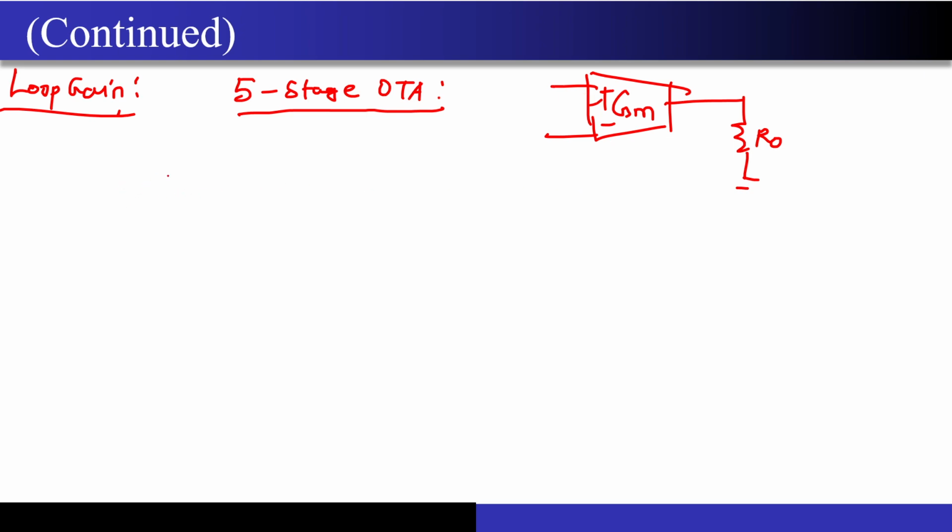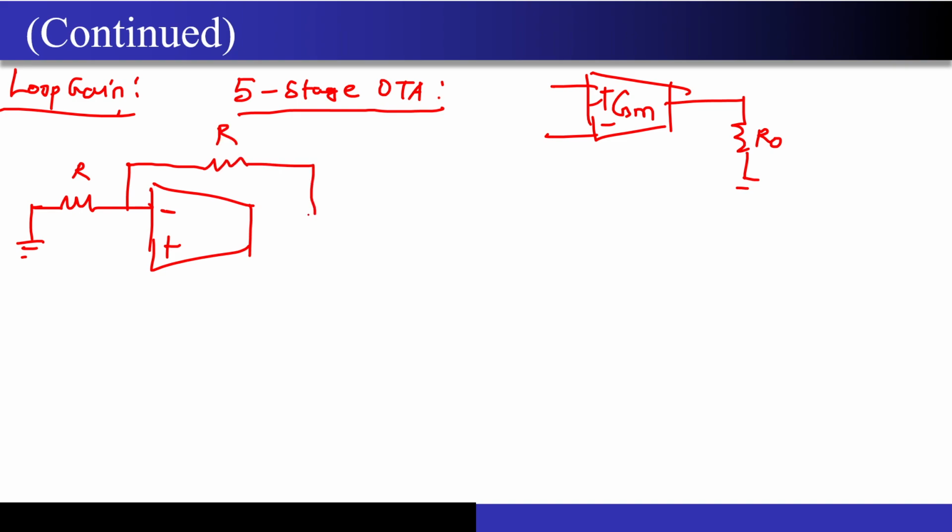So now what was the diagram that those guys have given to me? The diagram they have given to me was looking something like this, correct? This is R. The V bias will be grounded because I am interested in the loop gain analysis. I have to ground all the static voltages that are present in the circuit. This is R, correct? Then I had a CL over here. This is the V0, correct? And this is where actually I was applying the input, correct?